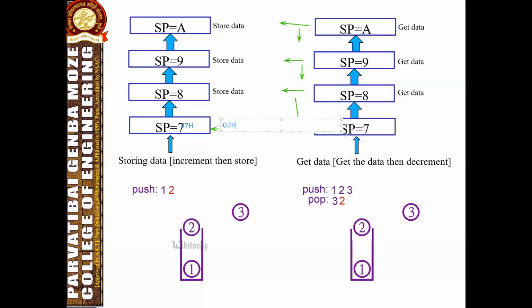The stack array can reside anywhere in the on-chip RAM, but its height is limited to the size of the internal RAM. Any part of the memory can be assigned for stack operation, but the size of the stack is limited and less than the internal RAM.